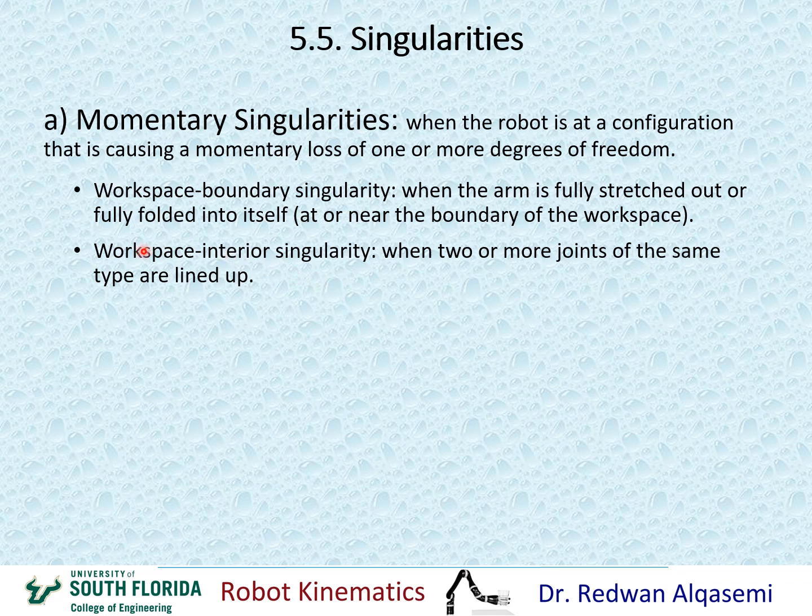And what I mean by lined up is that if you move either of these two joints that are lined up, the end effector will produce exactly the same motion. Whether it's two prismatic joints lined up together making the same action, or revolute joints that are both aligned together, if any motion of either one produces the exact same motion at the end effector, that means they are combined into one joint and you lost one of the degrees of freedom momentarily.